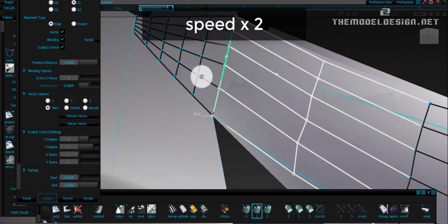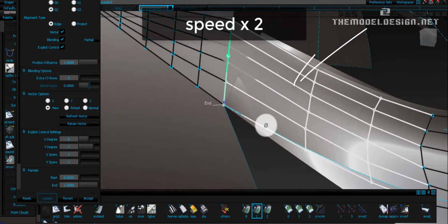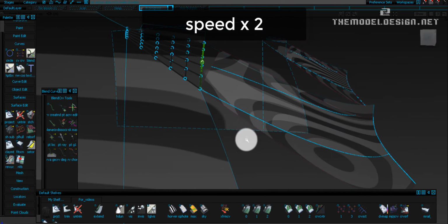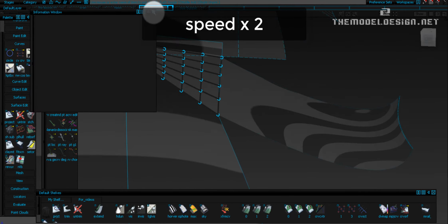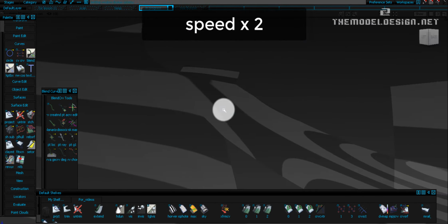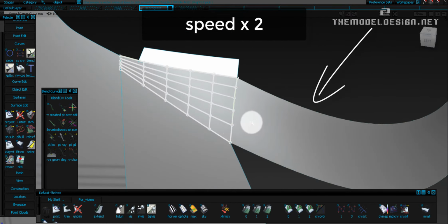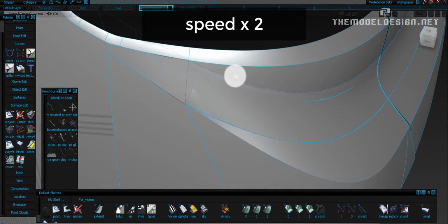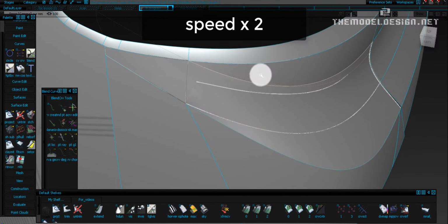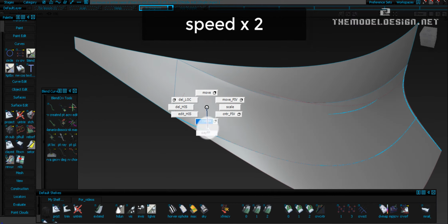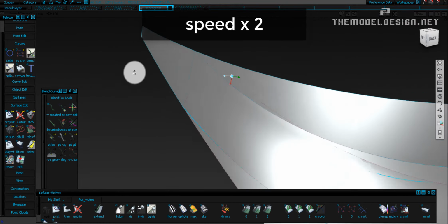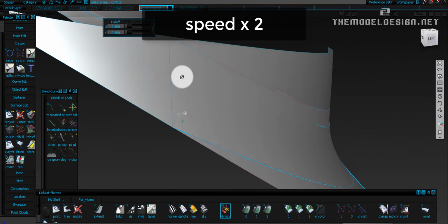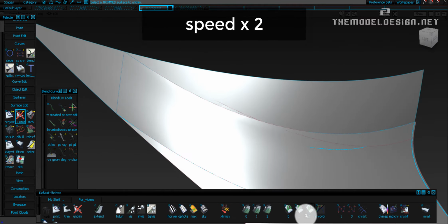Meanwhile, I still need to work on this area. I'm only kind of playing with this right now. I'm trying to align and see what happens. I'm certain that I will lose surface continuity on each side here and here, but it's okay right now. I mainly look at the highlight and CVs. Also, at this point I think of layout strategy. Basically, I think of how to slide the fillet surface to make this transition as easy as possible.